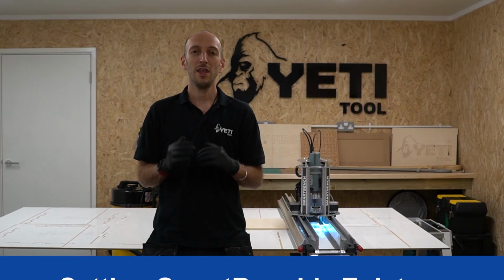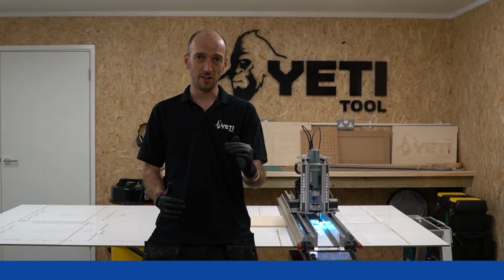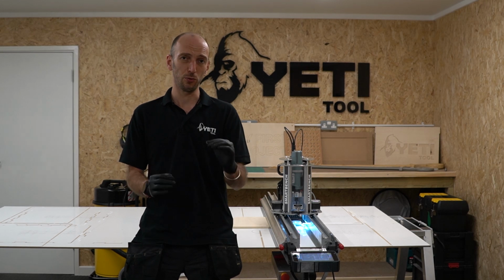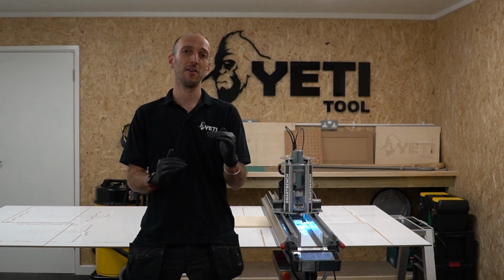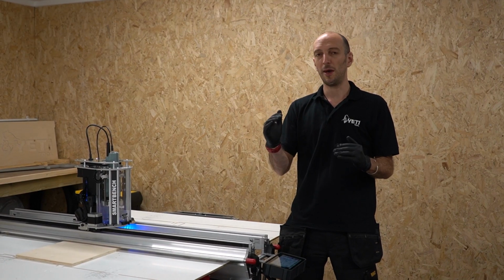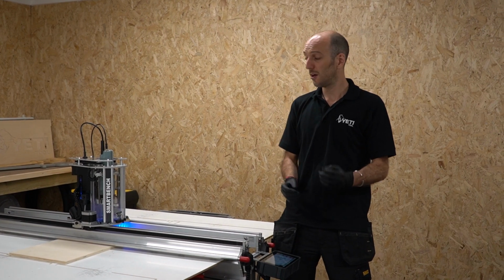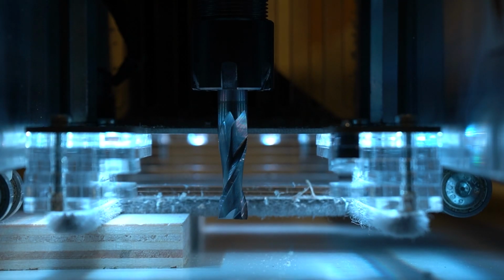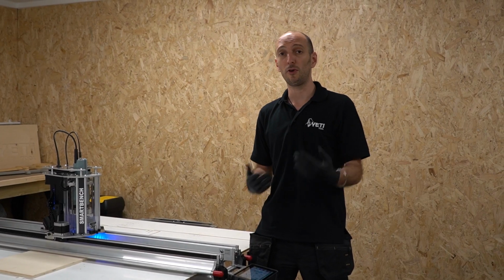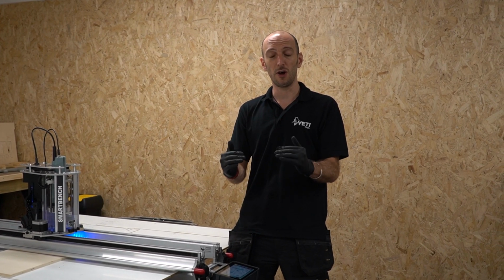This is a really good way to just make sure that your job file is going to be within SmartBench's workspace. Now it's time to set SmartBench's working datum in the Z-axis. What we're trying to do here is get the end of the tool to be at the same height as the job file's datum. To get your tooltip to be at that right height, you've got two options. You can either manually eyeball the position of the tool and then set it from what you see, or you can use the Pro plate, which will detect when the tool touches at the right height.